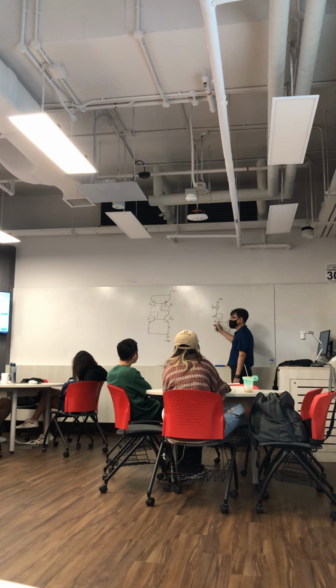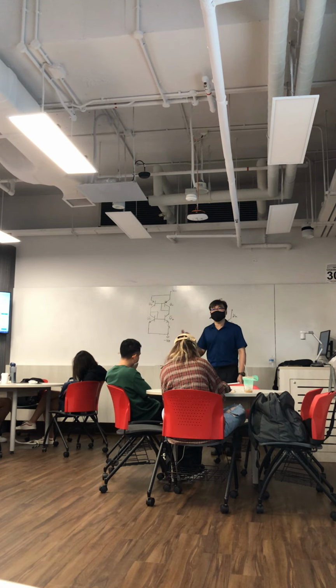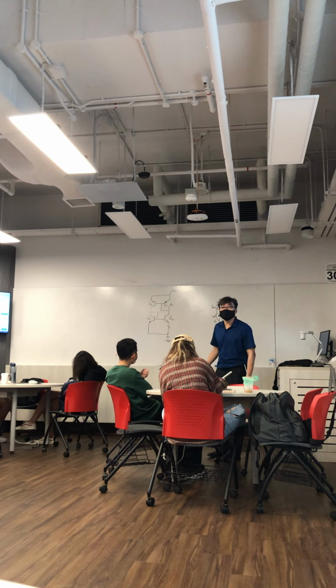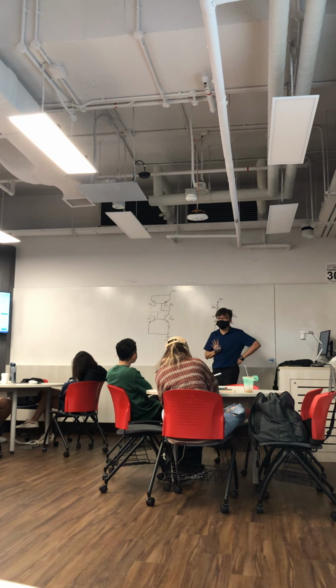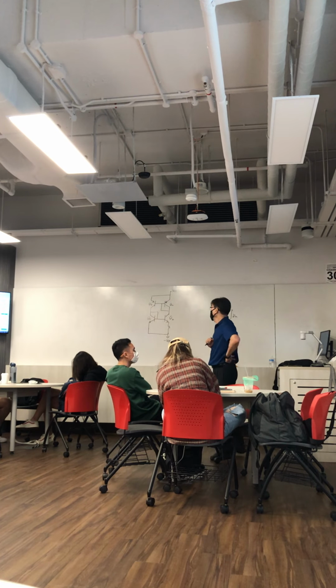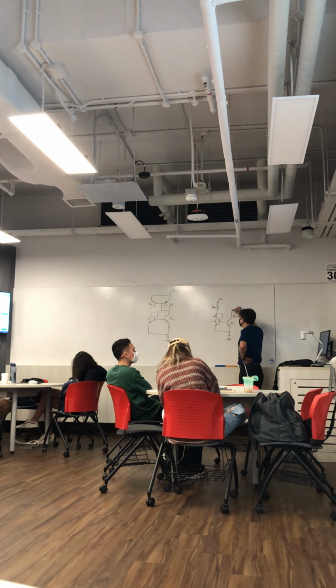So I can change the emitter area ratio to get different amounts of current mirrored over. So as long as I design this well, this current is approximately equal to this, then this will mirror to here based on the emitter area ratio. So far so good. So then, that means this point, theoretically, if this is a good current